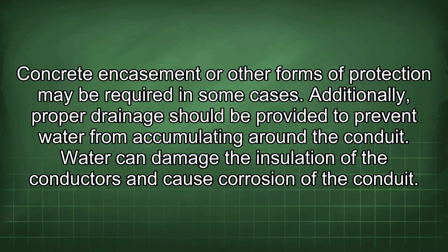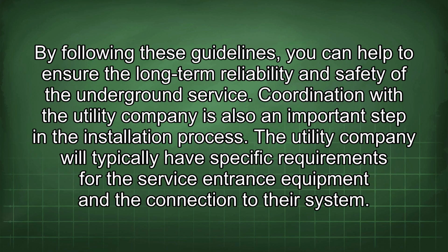Concrete encasement or other forms of protection may be required in some cases. Additionally, proper drainage should be provided to prevent water from accumulating around the conduit. Water can damage the insulation of the conductors and cause corrosion of the conduit. By following these guidelines, you can help to ensure the long-term reliability and safety of the underground service.